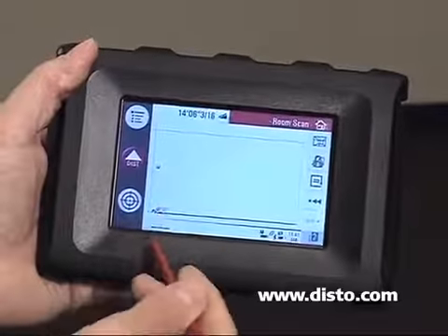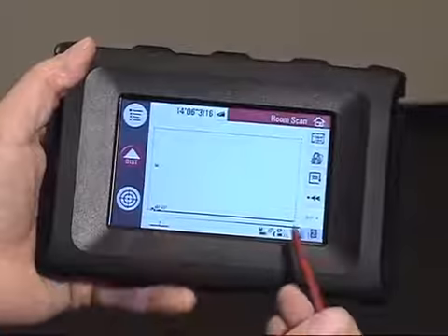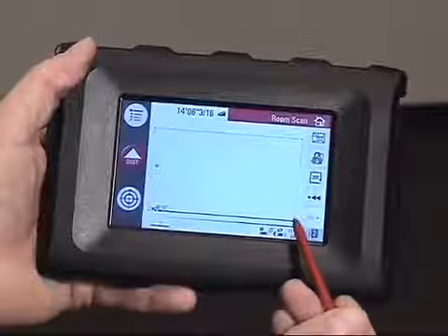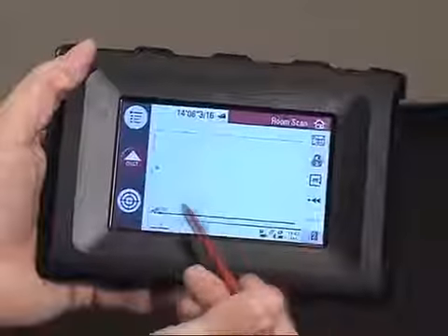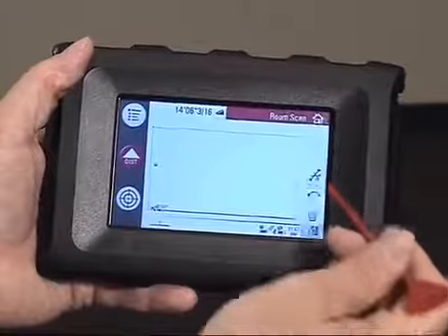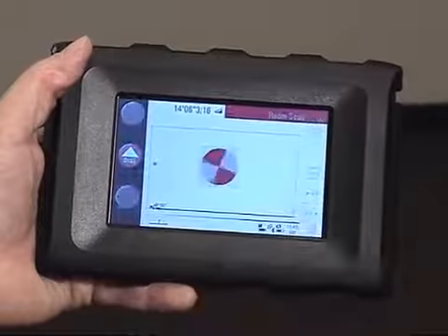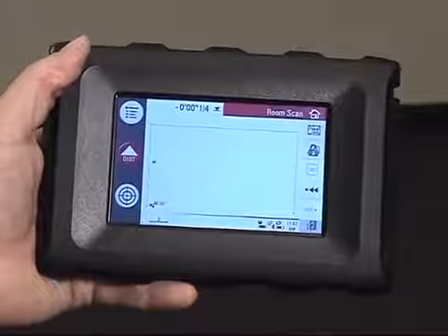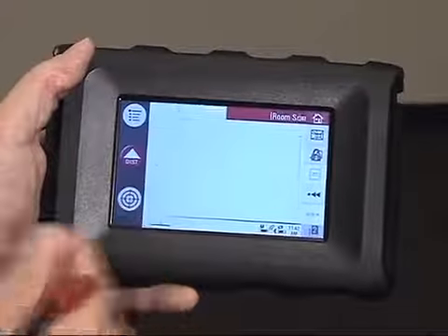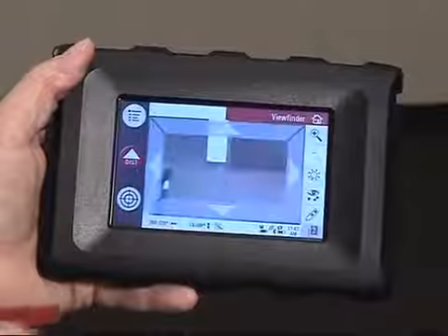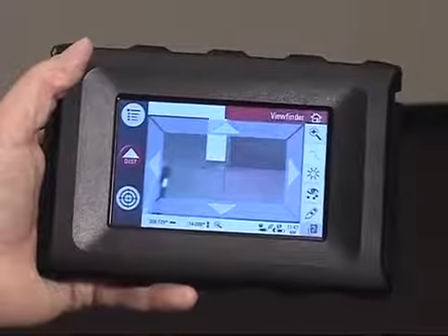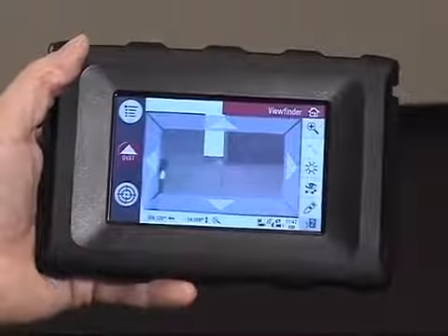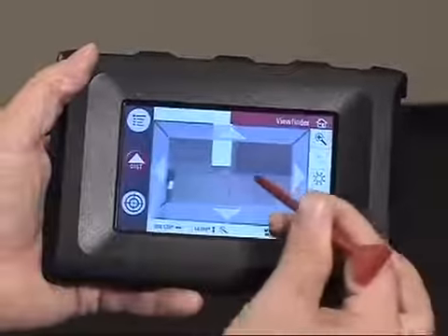So we've now done the bottom left corner. Again, the software wants to create a new line segment from the last point to the new point. So we're going to delete that segment quickly. Now the shortcut to locate something rectangular or square allows me to activate the view screen, and instead of measuring all 4 corners of this door, we're going to go up and measure the opposite right-hand corner. So we're going to drive the